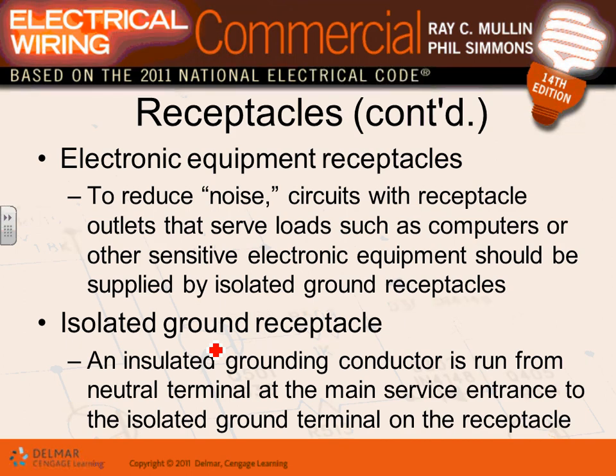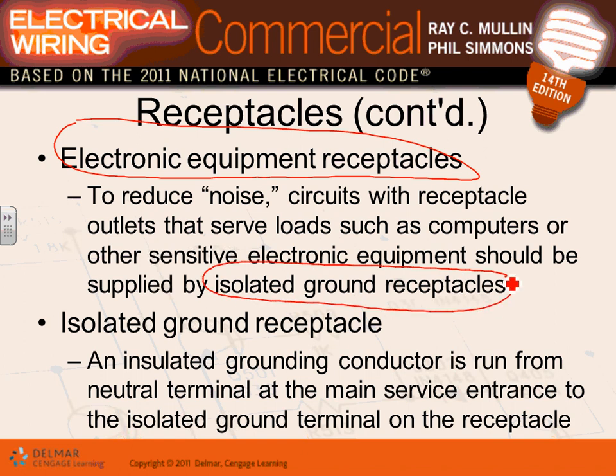Electronic equipment receptacles, guys. In this project, Adam, you will be having duplicate receptacles. In a few seconds, when I switch into laying out receptacles, I'm going to be talking about technology type receptacles. The technology type receptacles are meant to feed electronic equipment receptacles. In our project they are called technology type receptacles; here they are called electronic equipment receptacles. Who cares? They must have something called an isolated grounding receptacle.